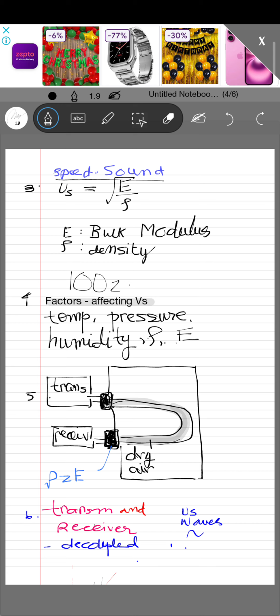Both the transmission and receiving systems are associated with piezoelectric material, and so whatever change of speed of sound is observed based upon change of temperature in the system gets reflected in terms of electrical signals.